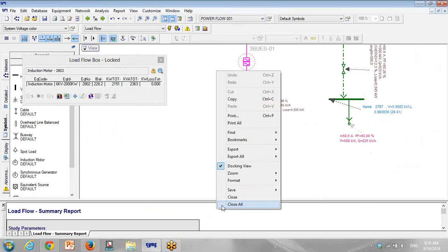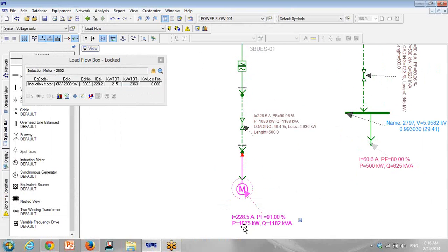So you can see the power at a frequency of 25 is 1000, but here we kept it, the power here is around 2100. So when the motor operates at half frequency, it will ask for half power.